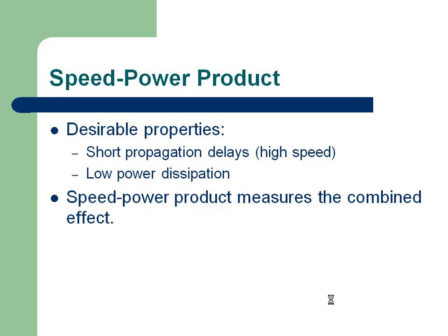Actually, more precisely it should have been called delay power product. And tell me what is desirable? Are you looking for minimum or maximizing this value? Minimizing this value. You want basically the smallest delay and the smallest power. In some cases, let us say the ECL logic family, delay is very, very small because ECL, emitter coupled, is the fastest logic family. But you are paying for power.